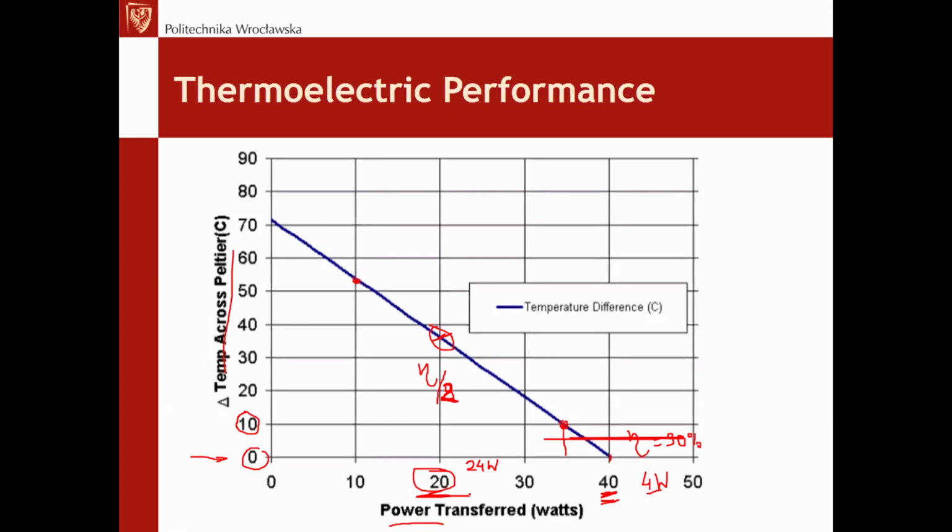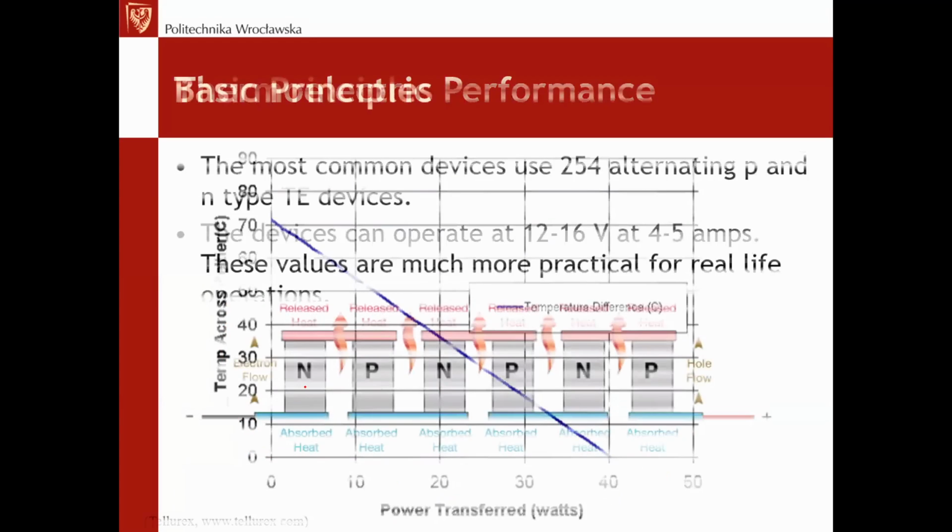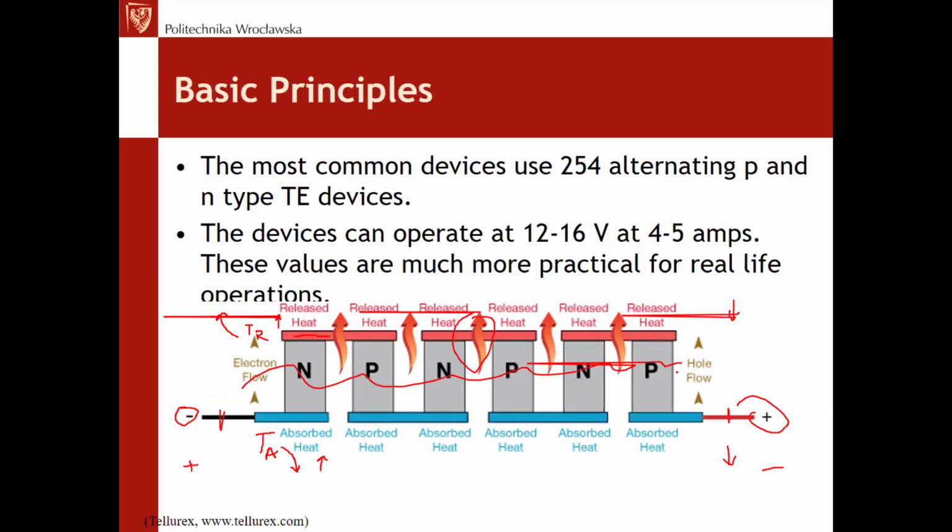Take a look. We have here, unfortunately, a positive loop, because the more heat we want to transfer, the more energy is dissipated here inside the Peltier, heating up the Peltier, and the more the Peltier heats up, the worse efficiency it has, and the more energy is lost in the Peltier elements themselves. So it's a positive feedback, and this is the major disadvantage of the Peltier element.